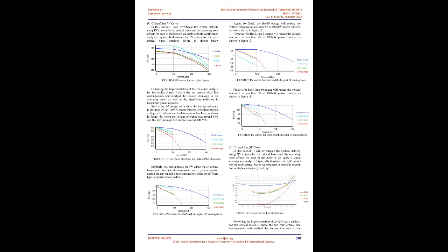As noticed, the use of DC load flow models provides acceptable capabilities for ranking the critical contingencies. For wide range systems, where the voltage amplitudes may not be a major problem, the DC load flow provides appropriate accuracy in terms of active power flows, ignoring the reactive power flow and transmission line losses.